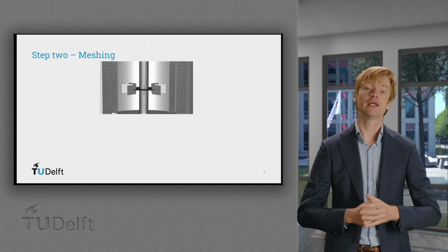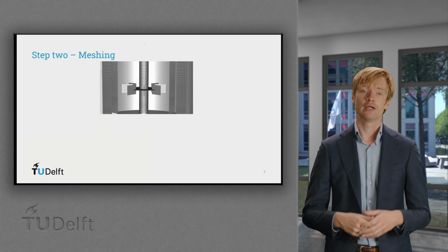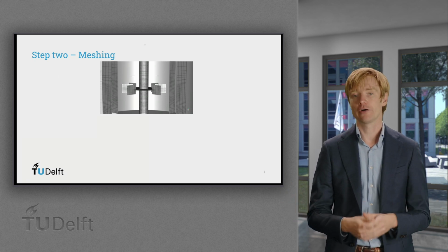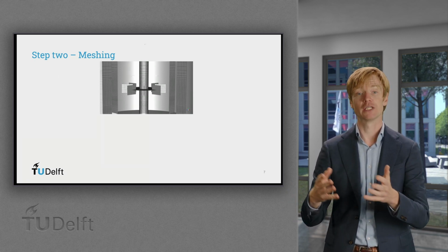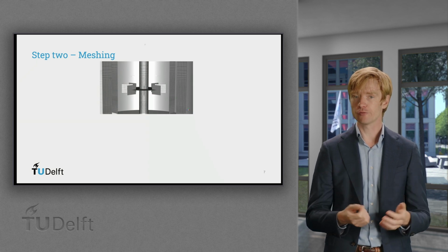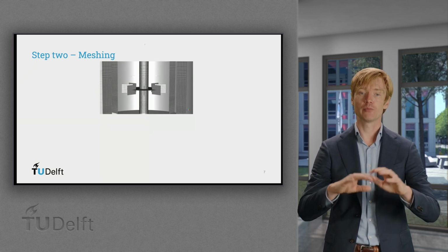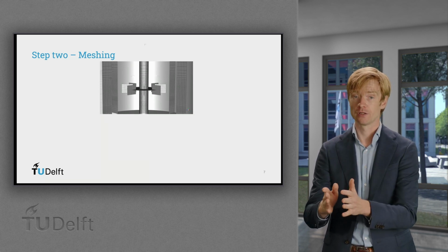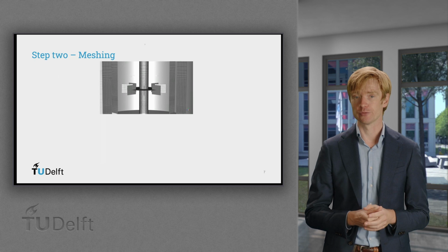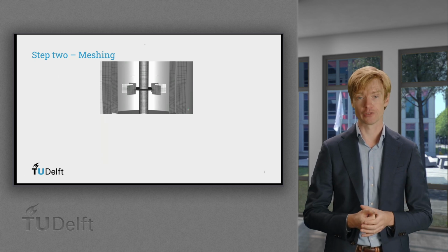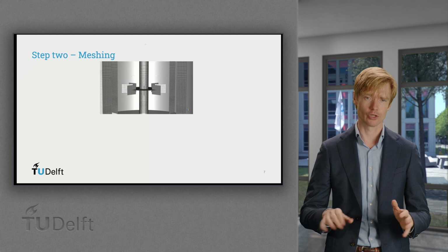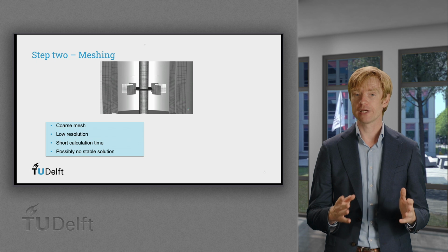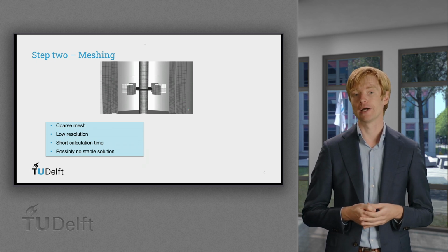Now, step 2 is the discretization step. It is important to realize that there's not one single CFD approach. There are different methods which perform this step in different ways. The majority of methods, however, discretize the geometric domain, the aforementioned segmentation of the volume into grid cells. There are methods that do not require volume segmentation and rely on other forms of discretization, but these are outside of our current scope. When the domain is divided into grid cells, we have to make decisions on the resolution that we want to apply.